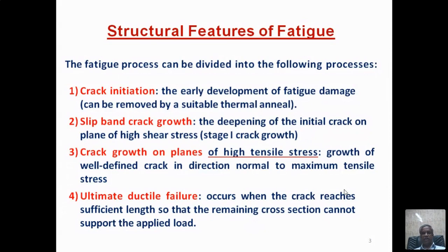Once the crack growth reaches a maximum level in the component, the component is separated. A crack means the separation of one component into two parts. Before the crack, it is a unibody; once a crack is formed, the unibody is divided into two portions. If the crack grows to a millimeter size, the component is not able to withstand the load. Even a load lower than the yield stress, even a smaller load, cannot be withstood, and the final failure will happen.